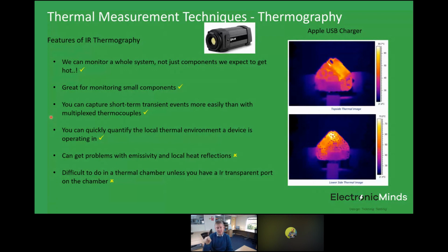And secondly, coming back to the point about the conflict with EMI, SiC and GaN-based devices typically operate at a dV/dt that is orders of magnitude higher than for silicon, so the amount of current pumped parasitically through your insulating layer onto the heatsink goes up massively. You have to be careful how you manage your EMI because of that effect. How you return parasitic currents generated onto heat sinks needs far more attention with these wide bandgap designs. It's a real challenge, particularly for GaN devices. We've found them quite hard to keep cool, and Jose talked about this in his webinar on Tuesday. Advanced packaging techniques for wide bandgap are starting to address some of those cooling challenges. Ultimately, it all becomes a big thermal challenge.